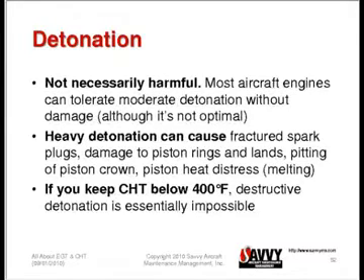But if the detonation gets heavy enough, it can start doing physical damage. It can fracture spark plug insulators, which can lead to really bad things, pre-ignition. It can do damage to piston rings. It can pit the crown of the piston, and in real extreme conditions, it can start to melt things. So we really don't want heavy detonation to occur.